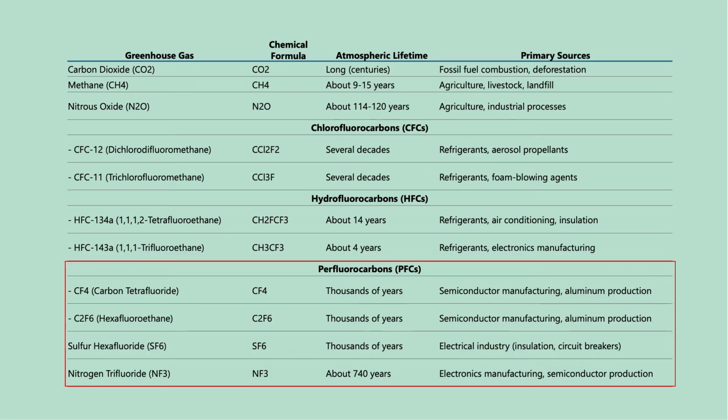However, SF6 is a very potent greenhouse gas with an extremely long atmospheric lifetime estimated to be thousands of years, making its global warming potential thousands of times greater than that of carbon dioxide. Due to its severe environmental impact, there is increasing pressure to find and implement alternatives to SF6 in the electrical industry.